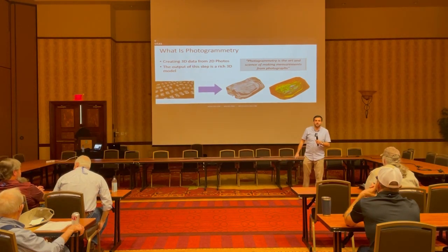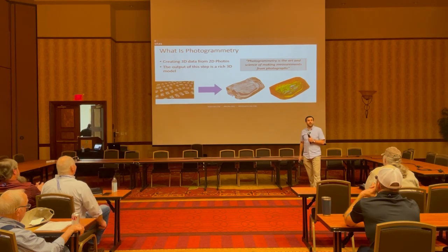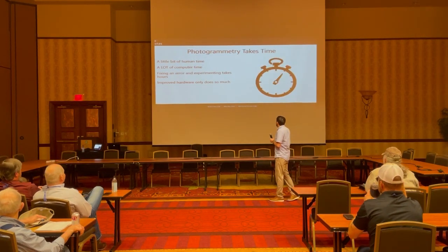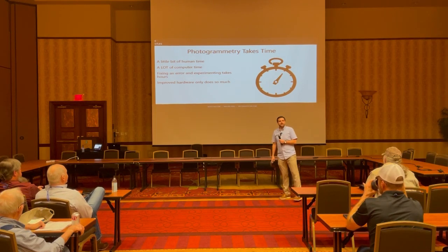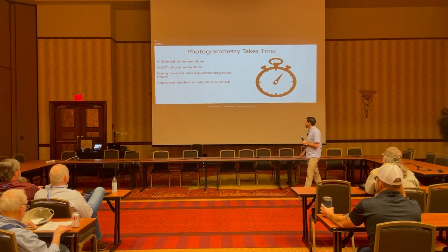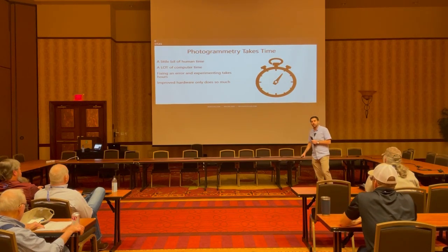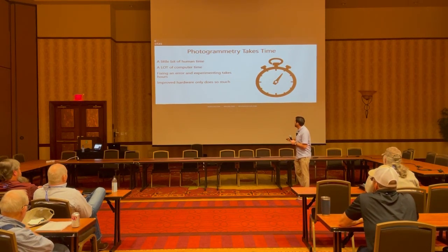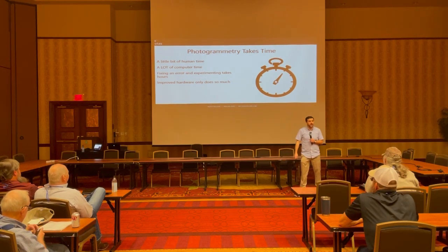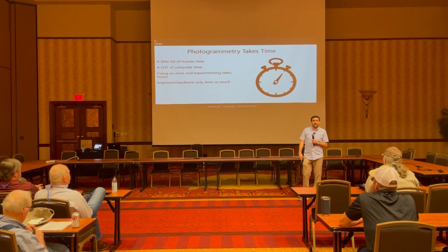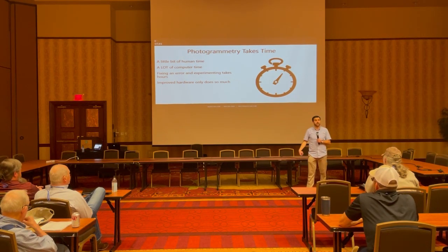So yeah, photogrammetry has been around forever, and even land surveying with photogrammetry has been around forever. But photogrammetry takes an awful lot of time. It takes a little bit of human time to mark your ground control points and set up your initial processing parameters, but a lot of computer time. Once you actually send something to a computer, larger projects can take easily hours and often multiple days to finish processing.